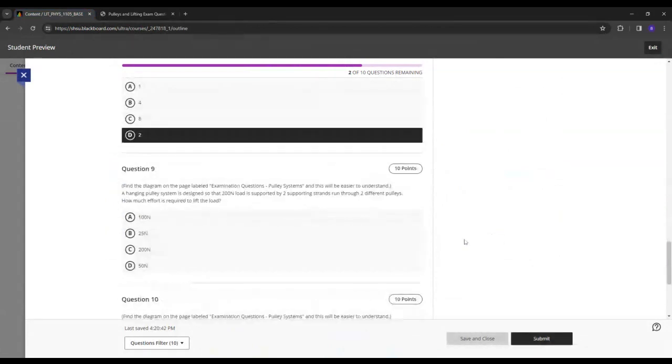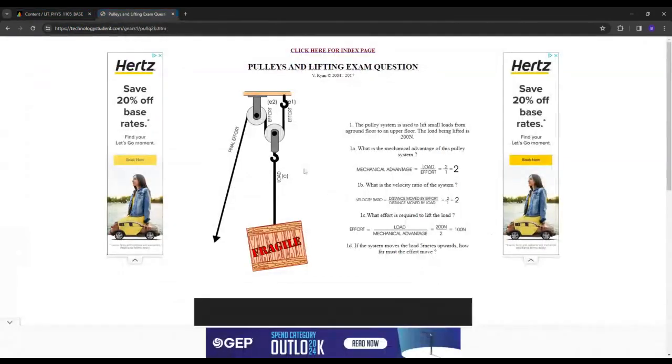Okay, so then if we want to see how much force that's going to take, you want to pick up 200 newtons of weight, so it requires 200 newtons of force. But that's combined from each of the efforts. So these supports here. If you pull with 200 newtons of force, you're going to get 200 newtons here and 200 newtons here, and that's going to sling this fragile crate in the air. We want to pick it up slowly, barely use enough force.